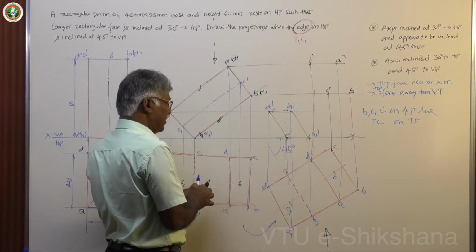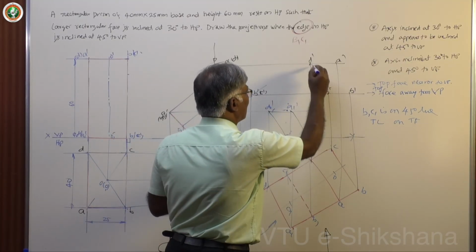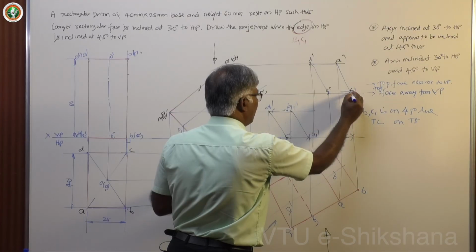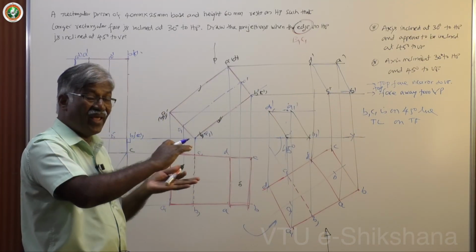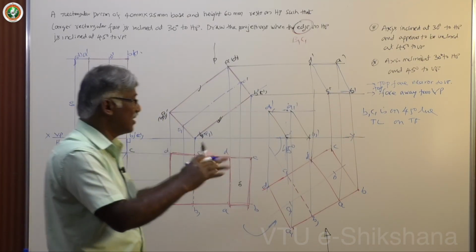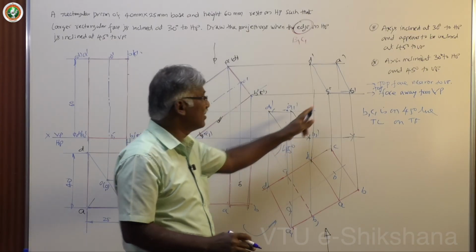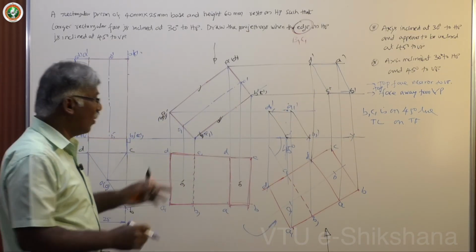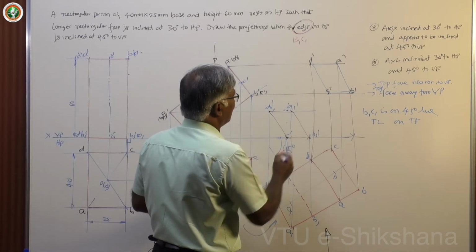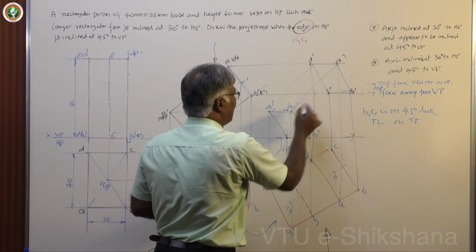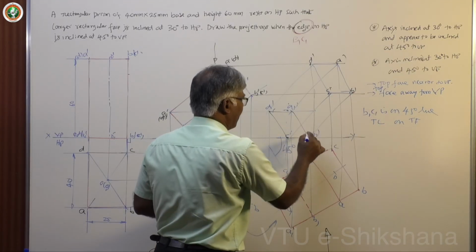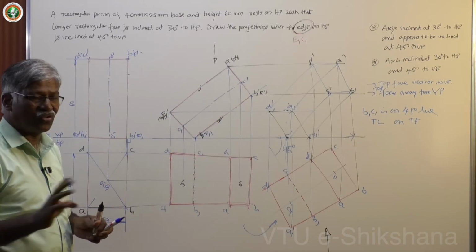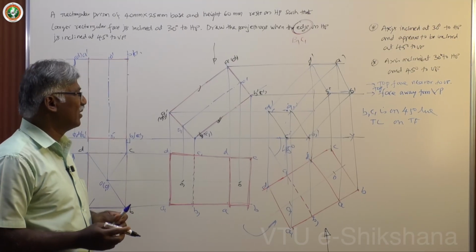Fine. Now join these. I use different color so that you can understand better. Two same size laminae are at some distance, 60 mm distance. This is projection of base laminae, this is projection of top laminae, top plane you can say. Now join DD1, AA1, CC1, BB1 in order. Systematically you must do. Then there is no question of any mistake you commit.